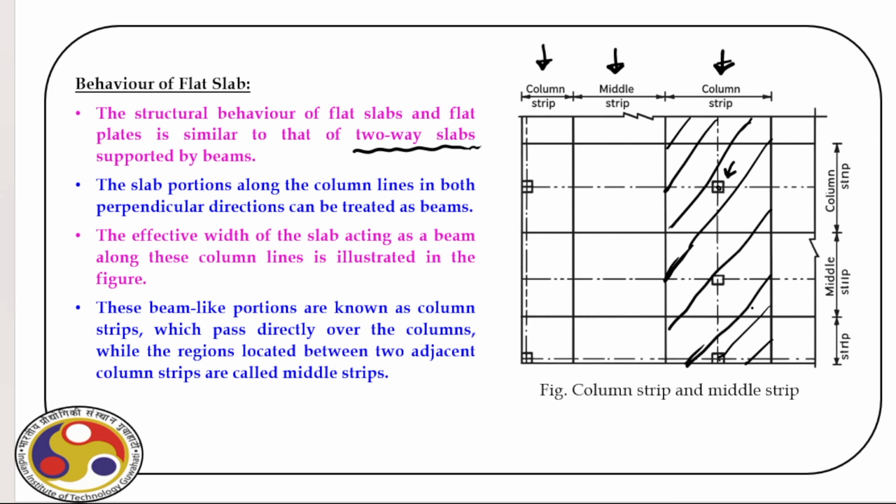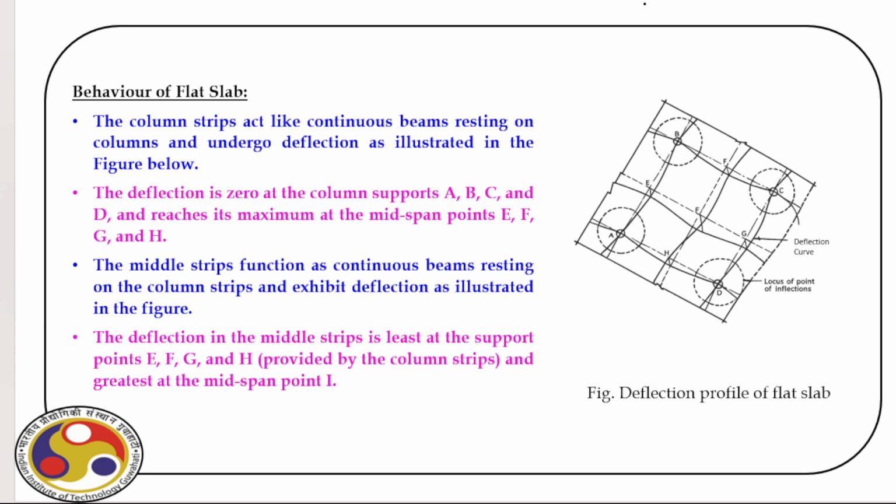So that we have to keep in mind, and you'll see as we design this flat slab, we'll consider hogging and sagging moment. So first point to be noted here, we consider this as a beam and then accordingly design, but we have to consider two orthogonal directions.